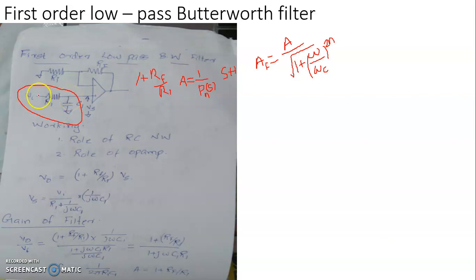And if the frequency of this input signal is exceeding the characteristic corner frequency, then it will be attenuated. In the stop band, this single RC unit is capable of providing a roll-off of 20 dB per decade, which is identical with the roll-off of 6 dB per octave.